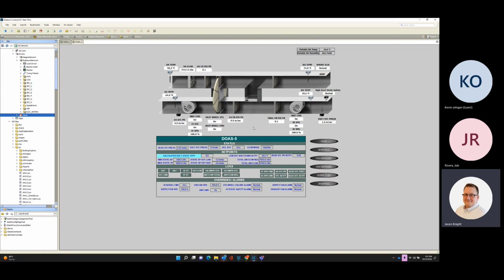And can you imagine the destruction? Let me emphasize this to your team. Imagine the destruction you can create if you go service this unit, put a VFD in hand, and forget to put it back in auto. If it goes to 10 degrees outside and this VFD on this unit gets left in hand, guess what? They ain't going to turn off. Yeah, you're going to break coils in the building.